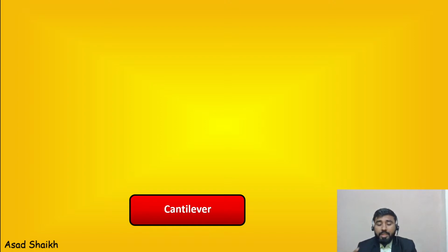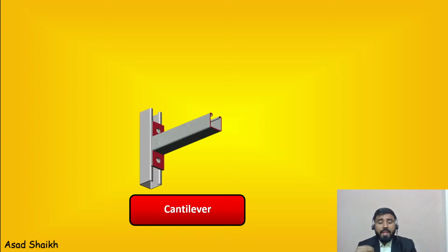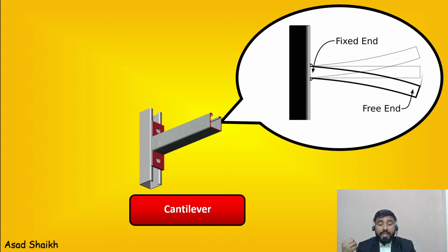Now in civil engineering you have something called a cantilever. Cantilever is basically a very simple design. Cantilever means a support which is given by the civil department, which is fixed at one end and the other end is unsupported. So if you have instrumentation trays which have to be laid, civil gives you this kind of support. One side is usually fixed and the other side is free, because the trays are not very heavy, so they can easily rely on the beam that is given.